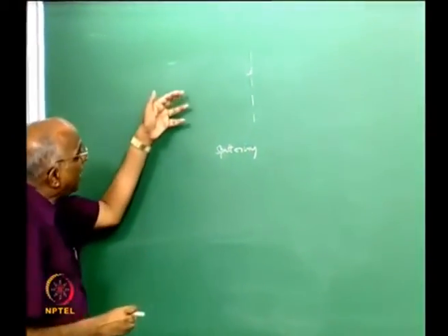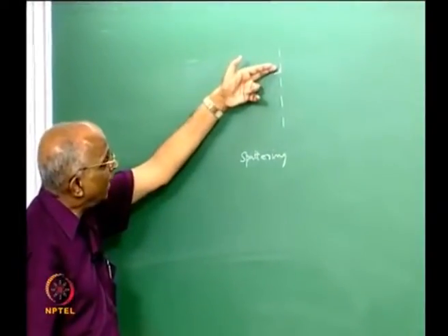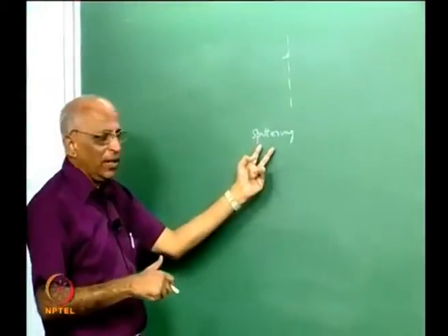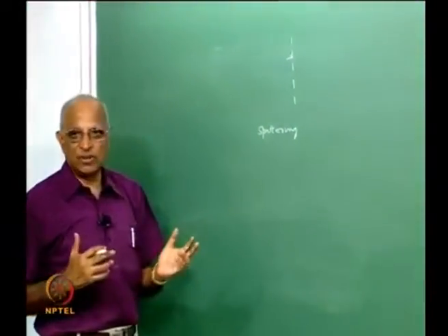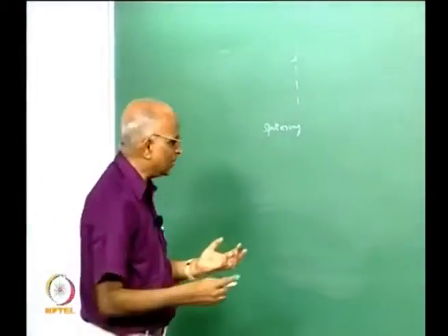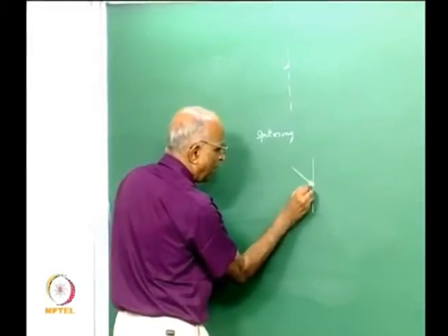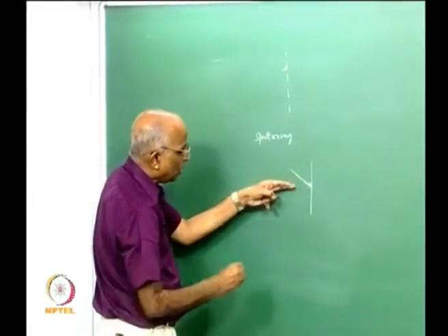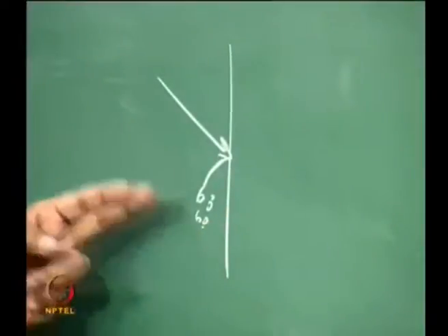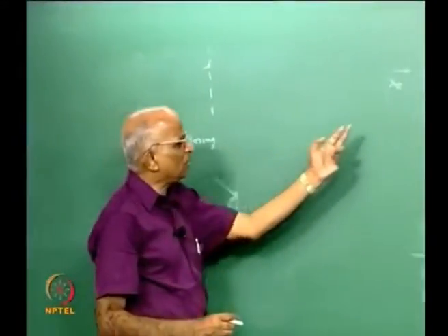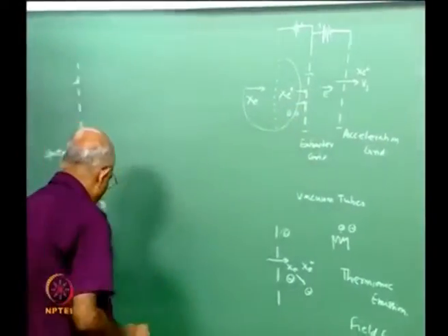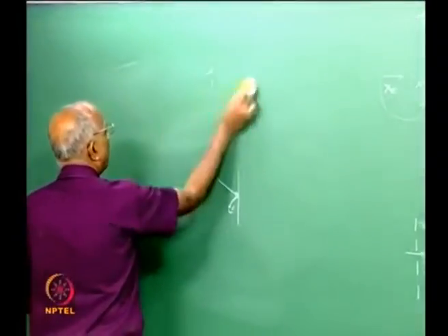That means I pass high velocity charges. High velocity charges, when they impact here, corrode the metal, and it is known as sputtering. I think we must remember this word sputtering, because when we talk of nanomaterials, one way of making nanomaterials is, I take a material, I allow high velocity charges to come on it, I generate very fine particulates, which are nanoparticles. Therefore, the sputtering erodes the thruster, and the lifetime of the thruster reduces. Therefore, one problem I can immediately say is a problem of sputtering.